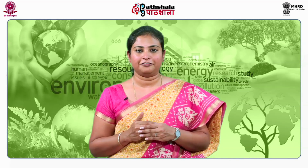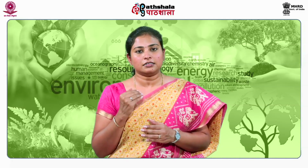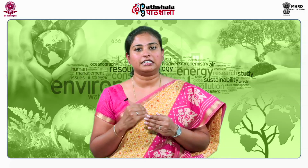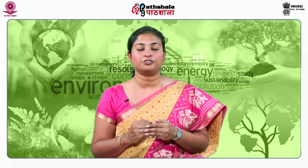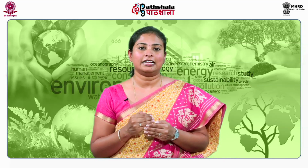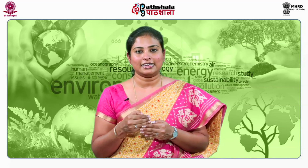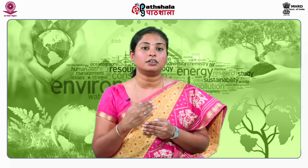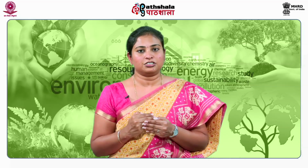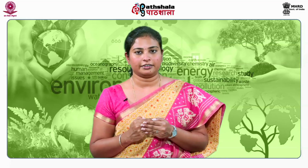The second type of landfill bioreactor is an anaerobic landfill bioreactor. The waste in the anaerobic landfill bioreactor generally undergoes anaerobic decomposition and results in the production of gases such as methane and carbon dioxide. They are generally referred to as landfill gases or LFGs. In anaerobic landfill bioreactor, the gases are recovered and can be converted or used in the form of energy. Greenhouse gas emissions are also minimized during the operation of anaerobic landfill bioreactor.